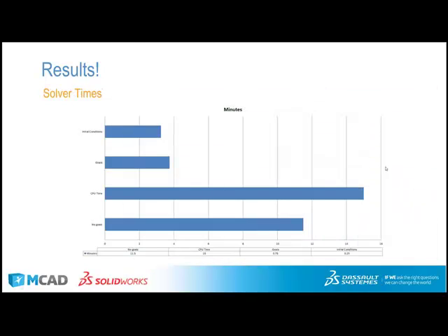So when you compare these on a graph, just to show the visual impact of it again, putting goals and initial conditions can vastly speed up your processing time just because the solver then knows what to look for. It's not intelligent enough to know that this is a channel flow and you care about mass flow and velocity inside of it. So if you give it goals and tell it what to iterate around and refine its values around, it knows where its stopping criteria is, and it won't unnecessarily iterate trying to get other very inconsequential values to converge. I mean, just look, a huge third of the time.